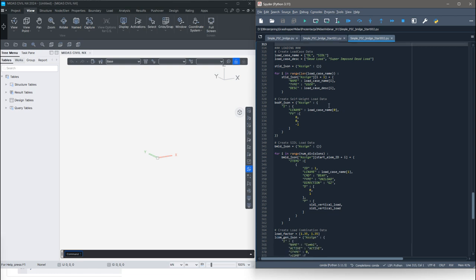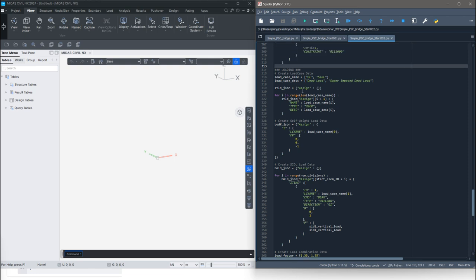In the next block of code, we run through a for loop with a range, with a length of this list with load case names, and we define body for the command to define static load cases. Here we type the name for the static load case. We take the ith element from this list.